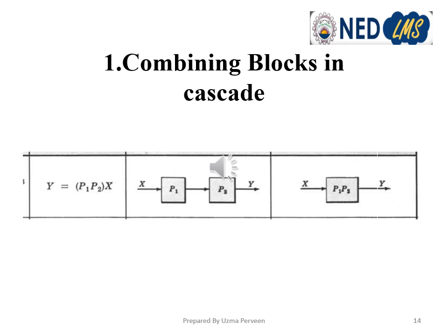Again the value of the output variable is y equals P1 P2 x. So this is the rule: whenever we apply some reduction technique or transformation technique to simplify the block diagram, the value of the variables should remain the same before and after the transformation.